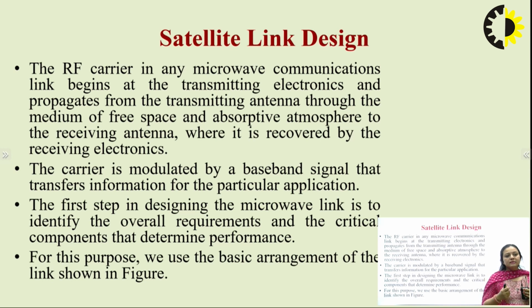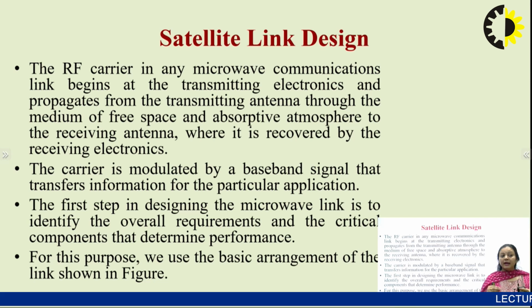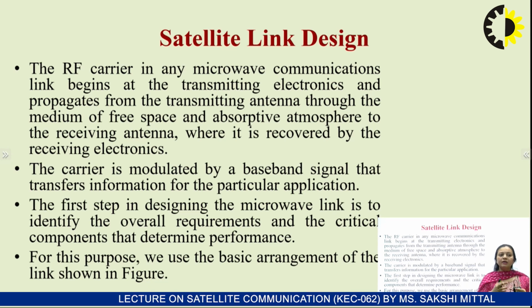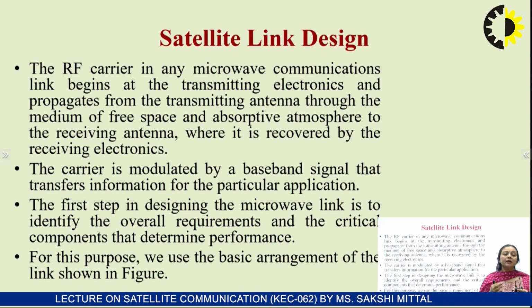Now the carrier is modulated by a baseband signal that transfers the information for the particular application. When you are transmitting information from the ground Earth station, you cannot transmit it as it is. I have to encode it for authentication purposes. Secondly, I have to modulate my data, and for that you need a carrier. So the carrier is modulated by a baseband signal, that is your message signal, which transfers your information for the particular application.